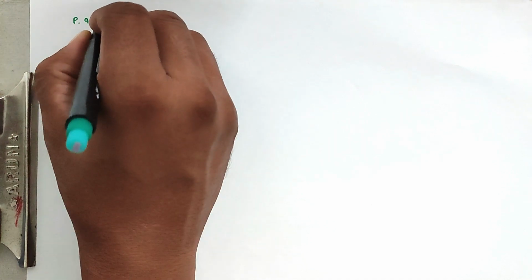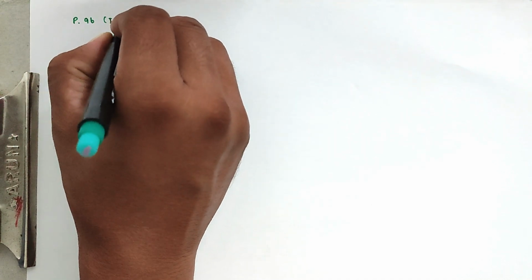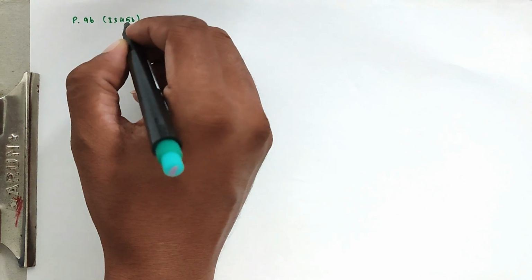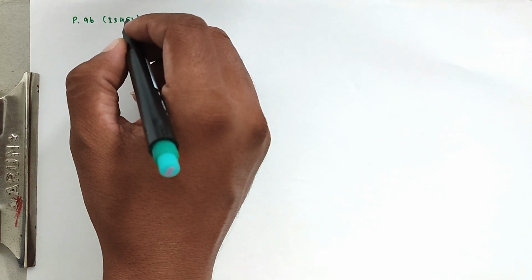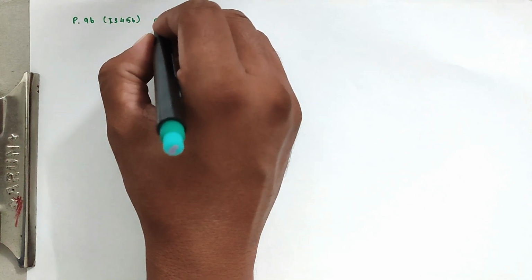Next, from IS 456 page number 96, we can calculate the limiting moment, that is Mu limit.